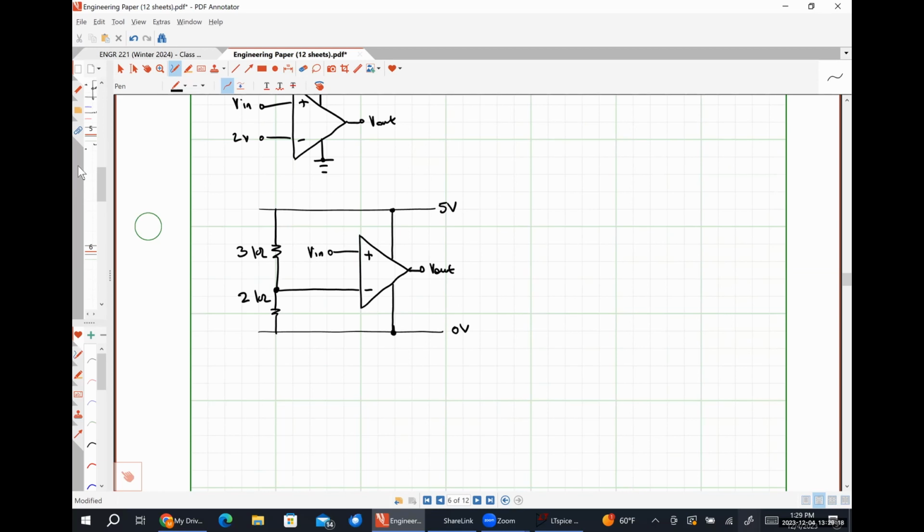So you chose to reconfigure the 10 and moved it into a delta. To go from a delta to a Y, you divide by 3. To go from a Y to a delta, you multiply by 3. So that should be 30, 30. Also, you take it to the delta, and then solve the Y. Yep.